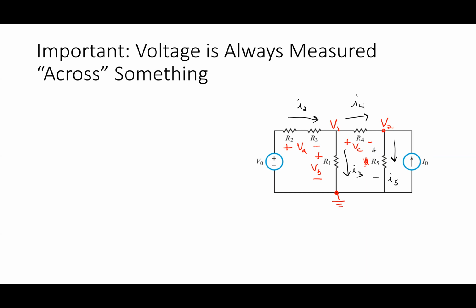But if I'm doing this, the reason I write the voltages across those things is it's important to me because I can say, if I look at VA right there, the voltage across those two resistors, I'm going to write my Ohm's law and say I2. How do I write I2? Yeah, VA over R2 plus R3. That is an Ohm's law. So this is my process. This is an Ohm's law statement that I just wrote for a resistor, okay?